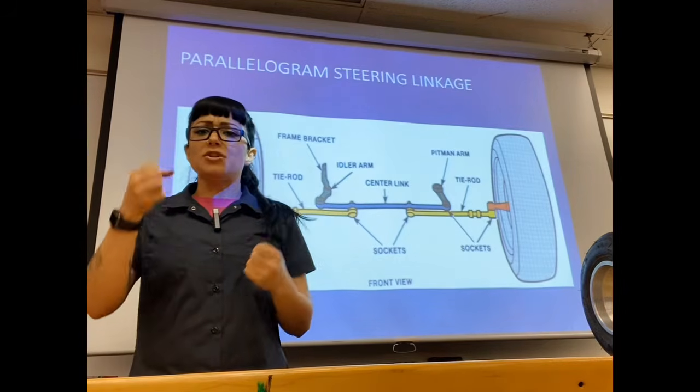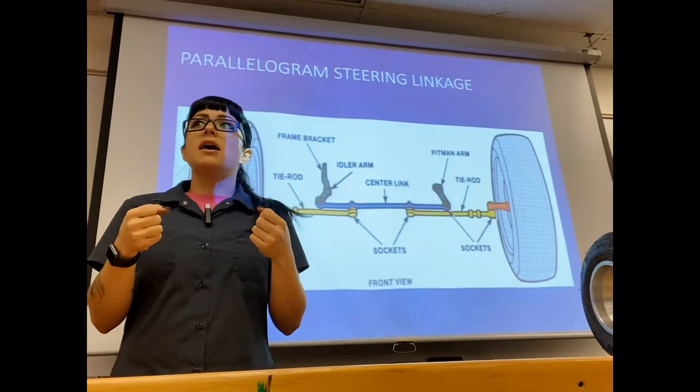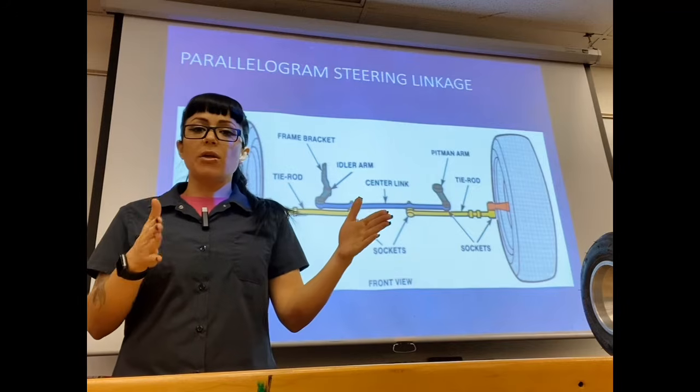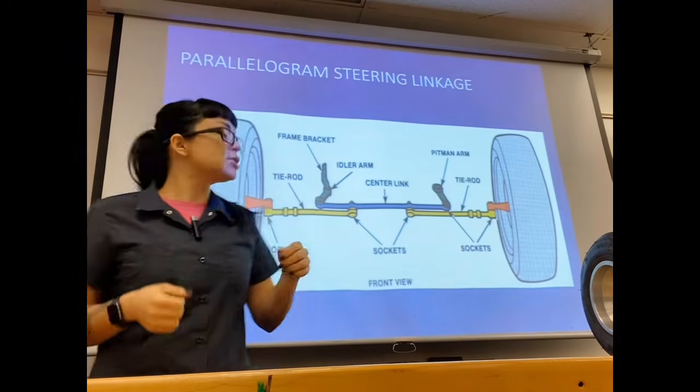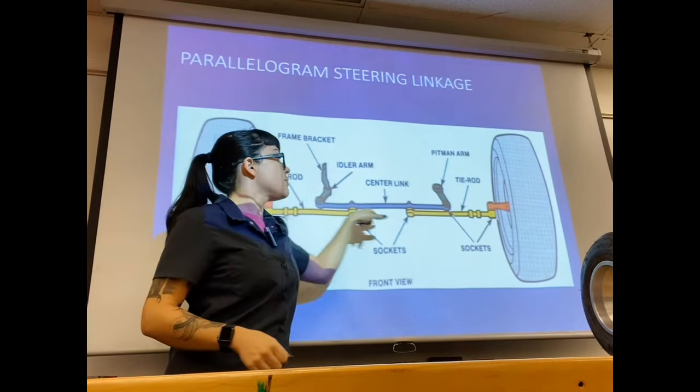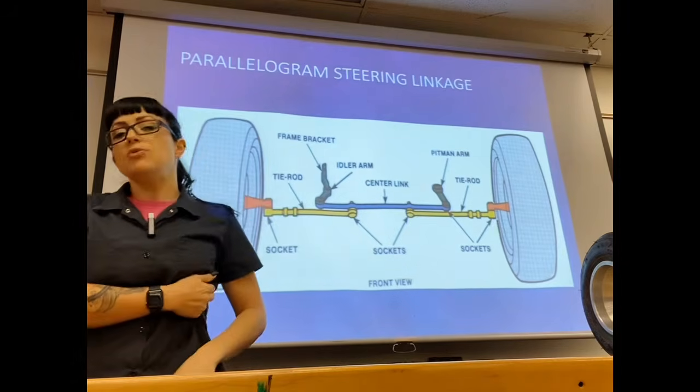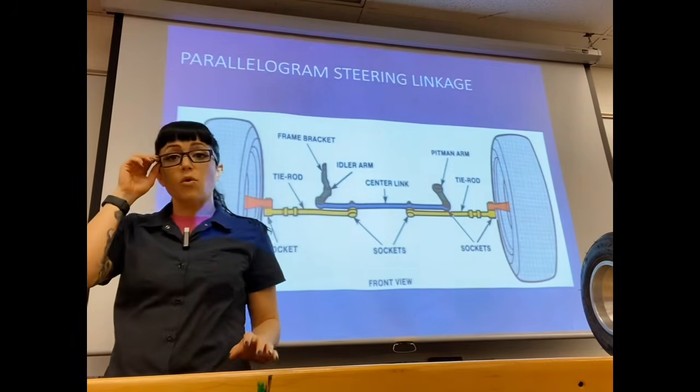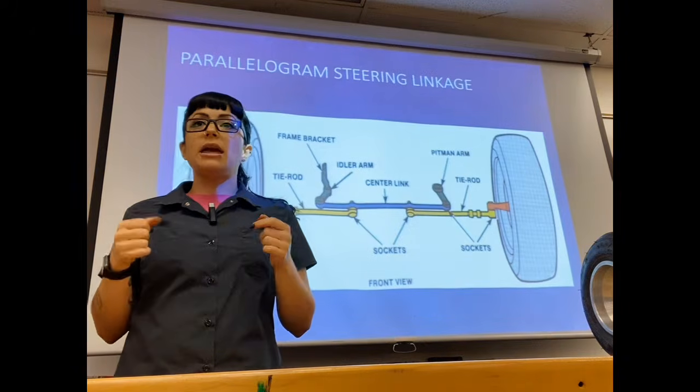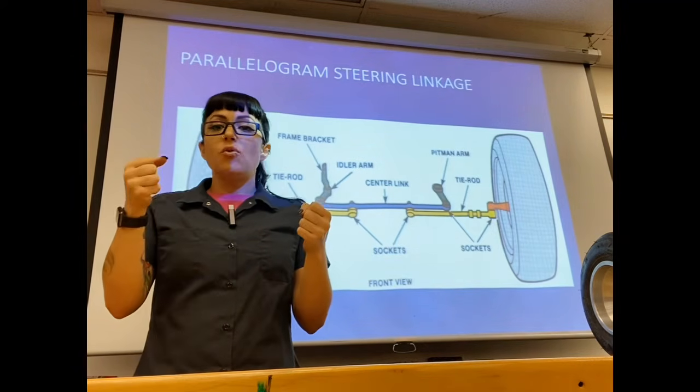And so eventually you are going to have a steering system where you can move the steering wheel and nothing happens at the wheels, because there's so much looseness in some of these joints here. You can usually pinpoint the looseness or the loose joint by doing a dry park test. So it requires 2 people.